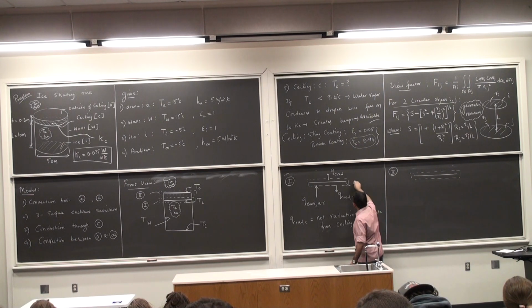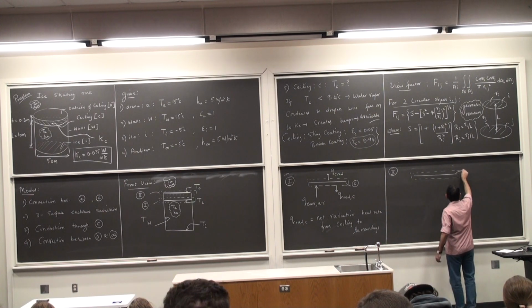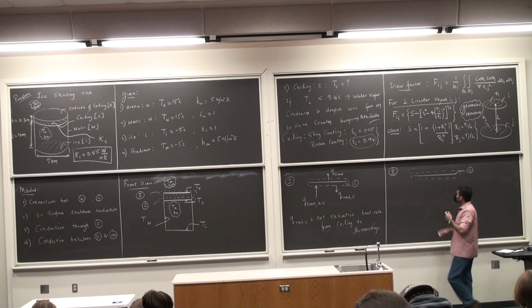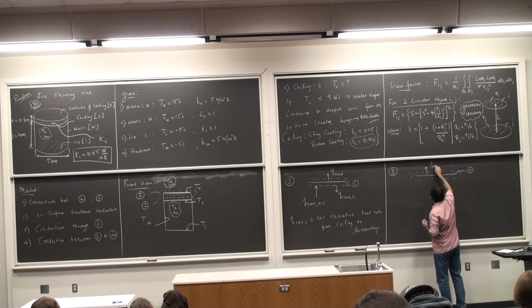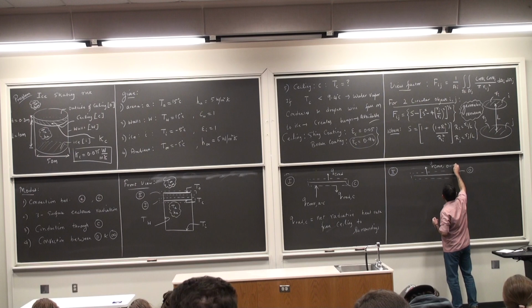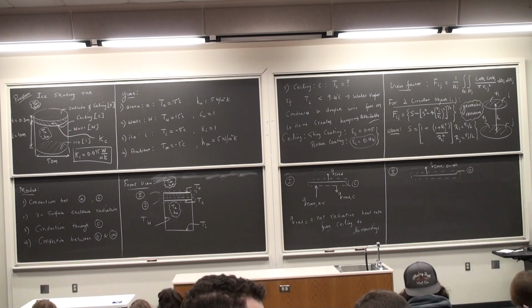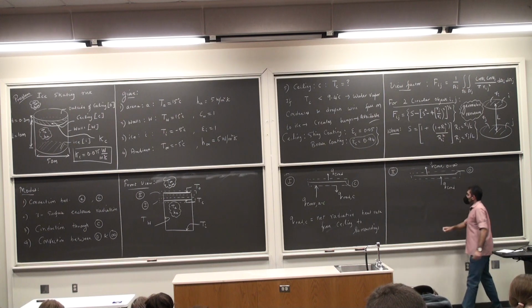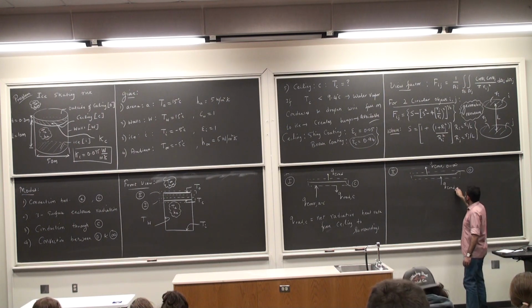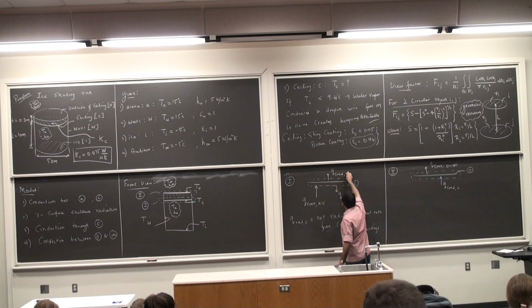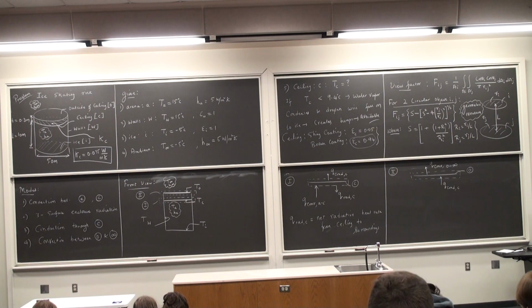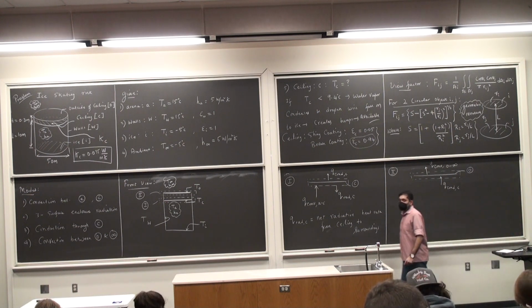So this is C here. This is O. There is obviously convection heat transfer from the outside of the ceiling onto the ambient. So Q convection from O to infinity. And then what else is going on? This is just going to be conduction heat transfer on the bottom face. Q conduction through the ceiling. So we can just give it a subscript Q conduction through the thickness of the ceiling. That's about it for the second control surface, control volume, or surface energy balance.